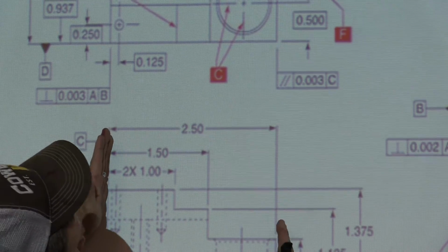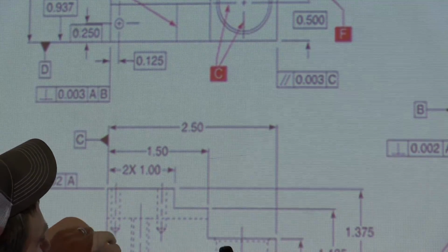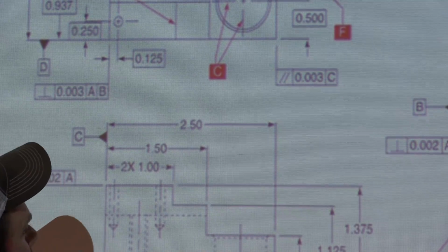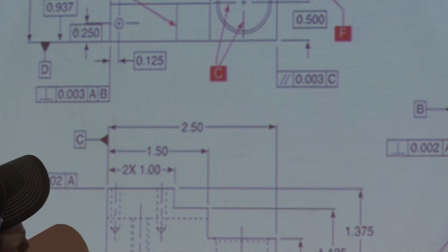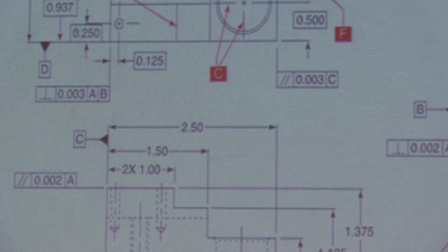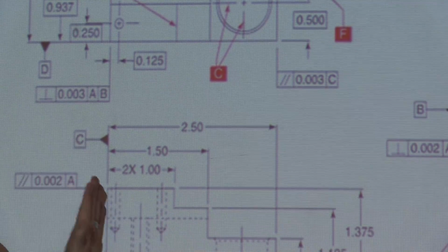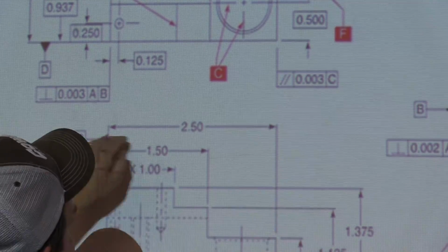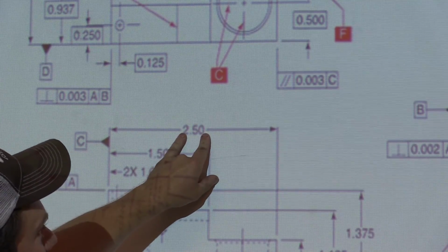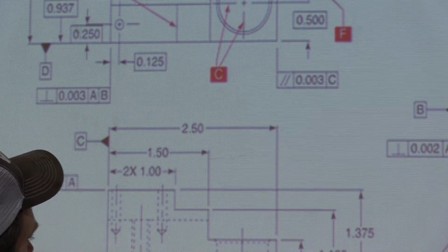Your extension lines are extending up beyond this part, so that way you are able to still see the full view and detail of the center part, okay? Because if we put all these numbers in here, if we put everything in this block, then we would not be able to see the details within the part. So we have to use extension lines to come up, and then we use dimension lines to give us the actual dimension with the leader arrow showing which part.